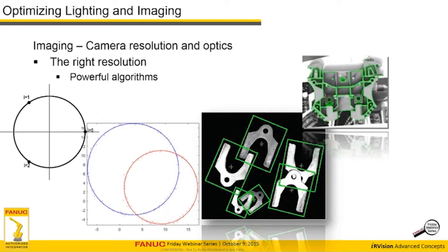Well, the bottom line is that those edges are very narrow edges, very small edges. They're not large gradient transitions. And so it may be the case, and I can't say for every individual application, that we're still not using an overdetermined equation, but that this particular part, this particular image, may need more resolution just because we need to get a certain number of edges on a feature, those little small features on that part.